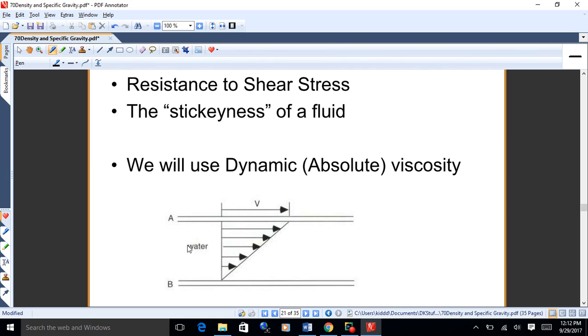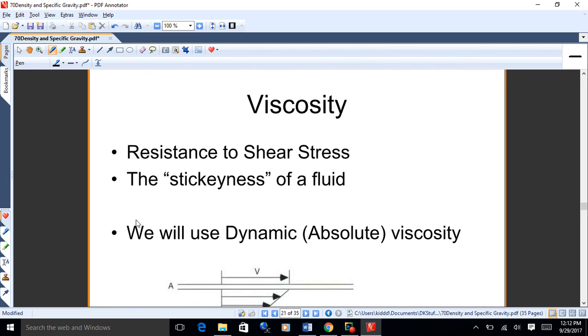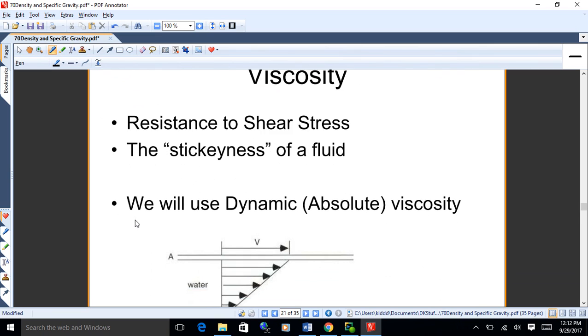And there's ways of testing this. They put a fluid between two plates and they see how hard it is to slide one plate across the other. That's the actual way of testing that. The units on it are kind of funny. Now we use viscosity because it indicates how hard it is to push a fluid, a lot of times through a pipe or something. You tested similar to friction? Yeah, right. The units are a little different because you're using shear stress and some other things. But yeah, it's a kind of a friction test.